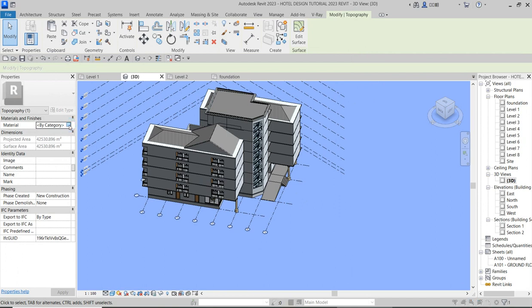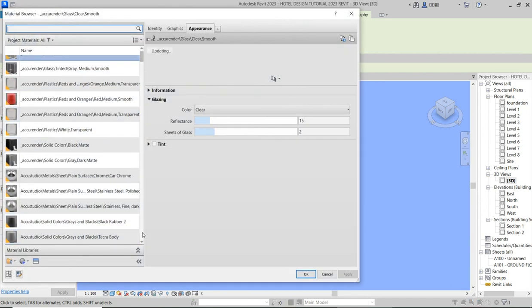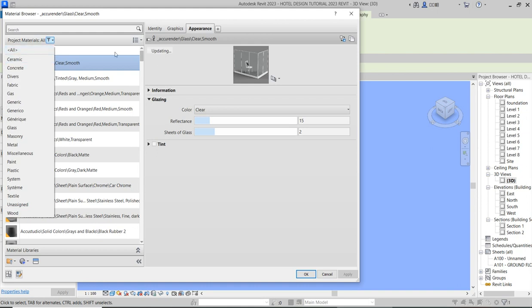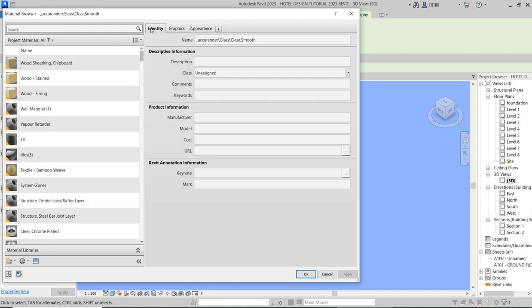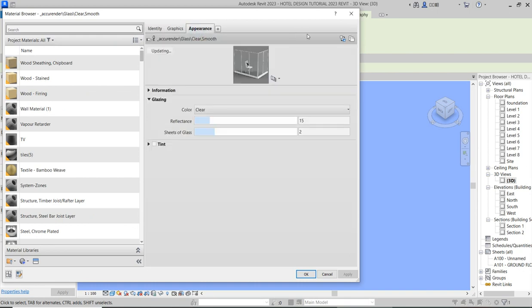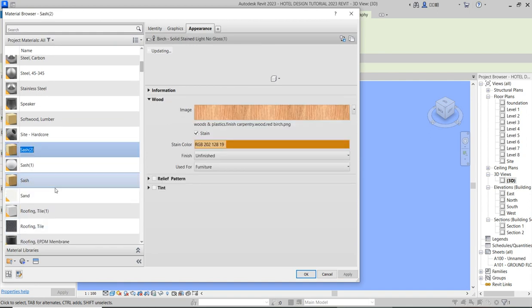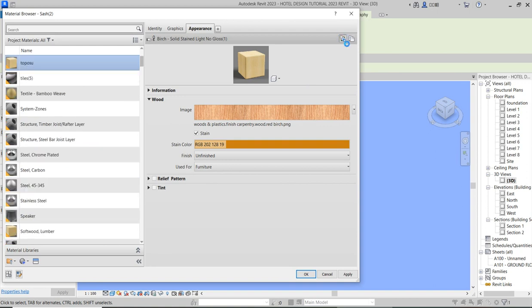But I just want to change it to some simple grass, because I don't fancy the whole procedure of that grass. So I want to use this one, and say identity, appearance. Let me create something, or just click on the material and say duplicate. So we call it Toposurface, just leave Toposurface like that. So now you click on appearance, you change the appearance.